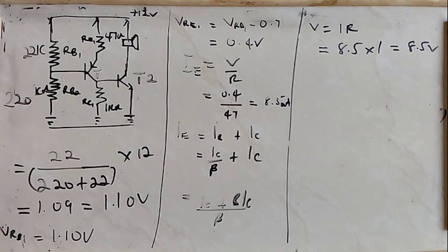The rule of thumb here is that in your bid to design this amplifier, the collector should sit midway of the voltage supply. So over here, our voltage supply is 12 volts. We have to program the circuit to sit at 6 volts, which is midway of the power supply. So instead of the 1K resistor, we have to do a calculation to see what value of resistance will cause the circuit to sit at half of the power supply.